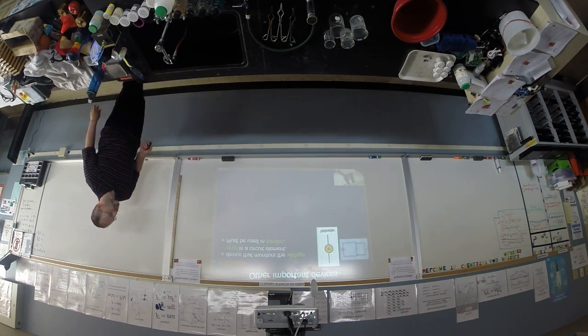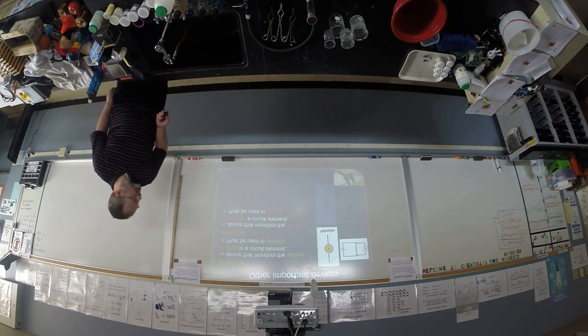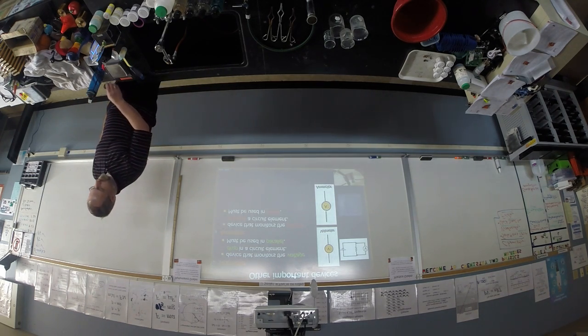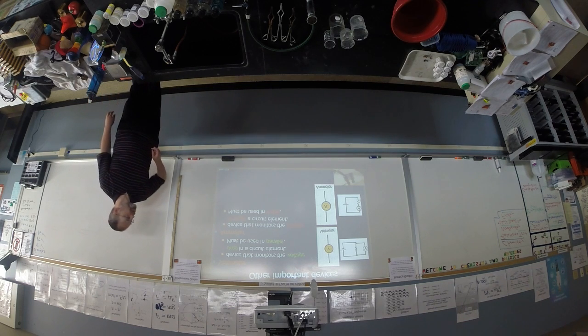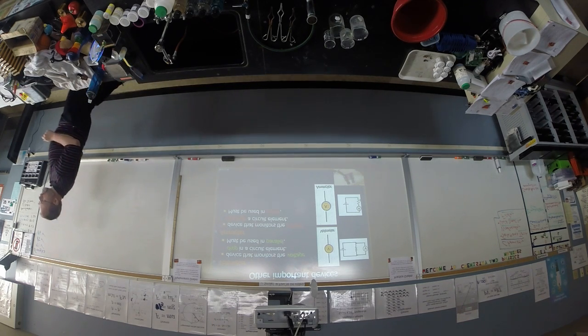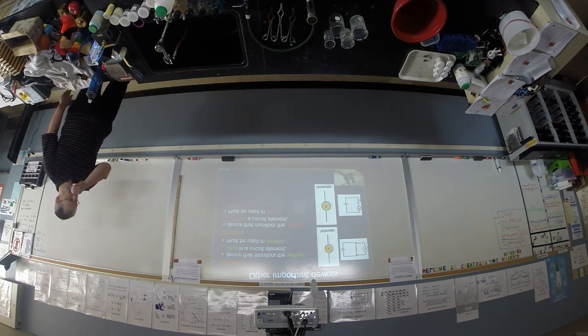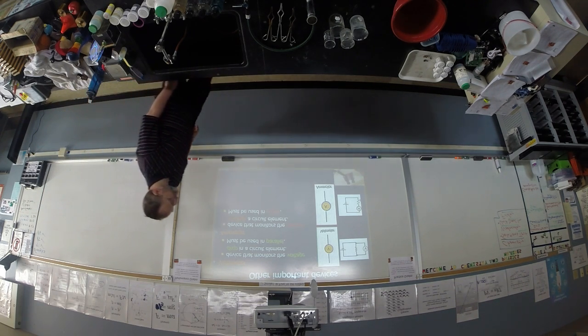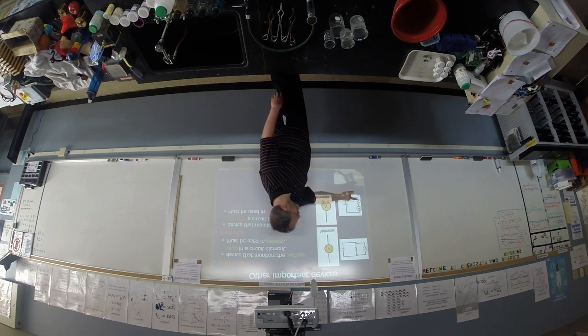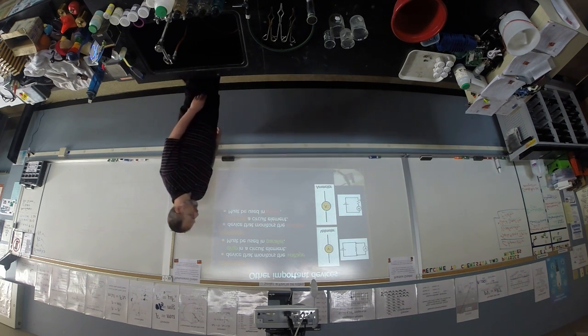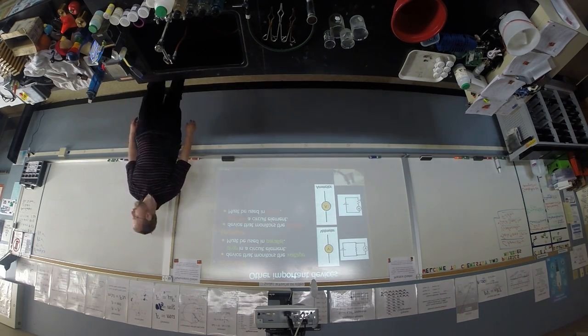Other important devices, ammeters and voltmeters. So I talked briefly about ammeters and voltmeters a while back. An ammeter, you're going to put in series. A voltmeter, you're going to put in parallel. You wire them like this, depending on your target device.